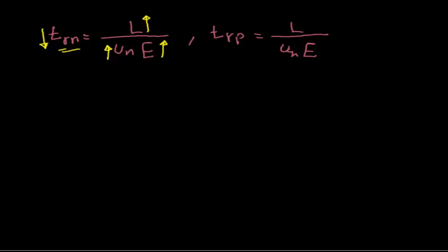Usually in a photoconductor there will be thermal noise, and that is due to thermally generated electron holes. So that's why we usually operate the photoconductor at low temperature.